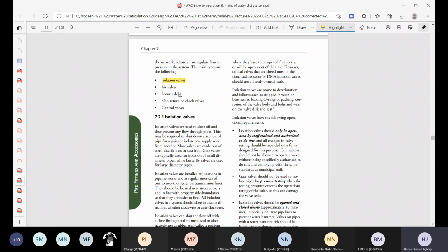If you have a plastic pipe or a thin wall pipe, because you now have a vacuum in it and you've got soil pressure on the outside, the pipe could quite easily collapse or deform or get damaged like that. So you can see that if you have a scour valve in it, then surely you're going to need to put a vacuum release valve in your pipeline system.